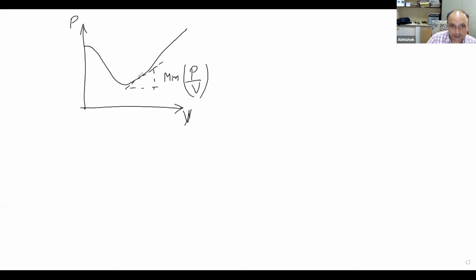And the point where this actually happens would correspond to my velocity for best range, or as I have been calling it, mu y, or even Vy in my derivations. So this corresponds to best range condition. Again, the way we said earlier, that was the point where I have minimum power. At that point my profile power was less, so I ignored the profile power component. So I'll continue doing the same thing here. Although at this point my profile power may still be more than the induced power, I simply want to get a nice simple formula.